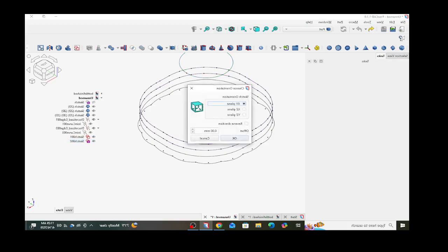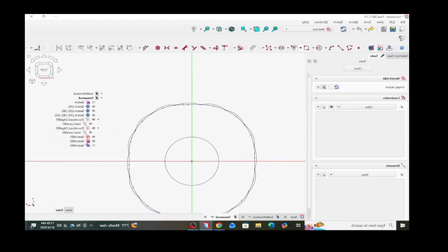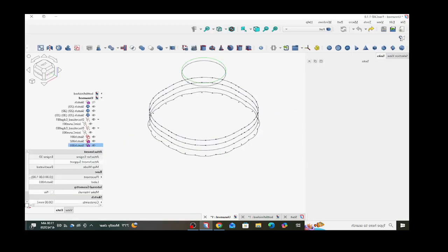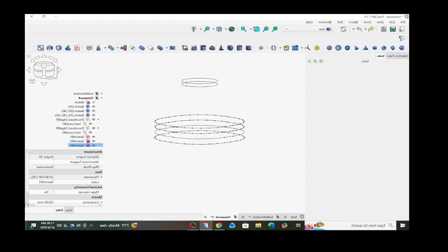And then I'll create another sketch and offset it to 53 on the XY plane. Create another 30 millimeter circle. This is just for tangencies, just to create tangency in the completed neck. So you need two sketches. Now